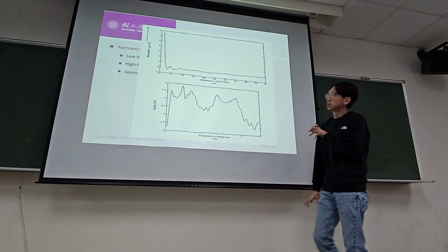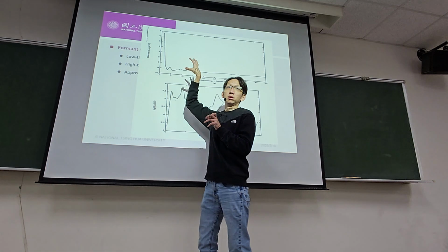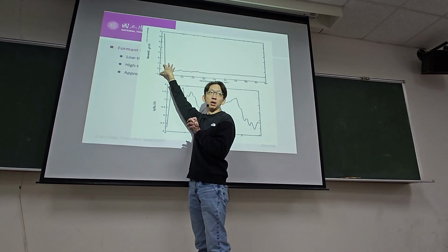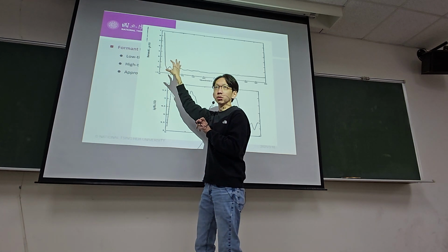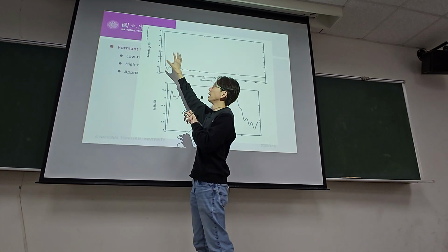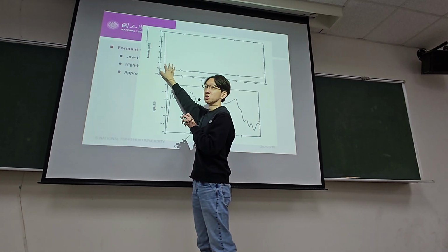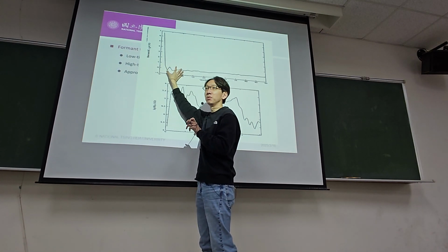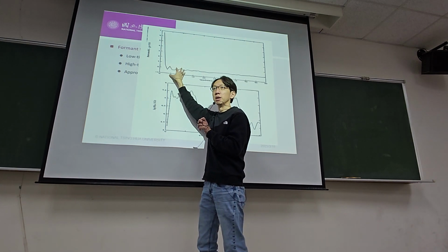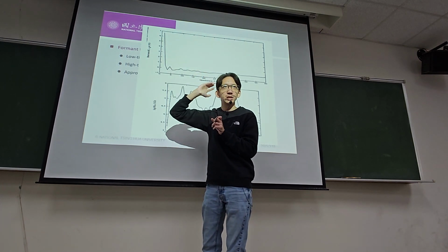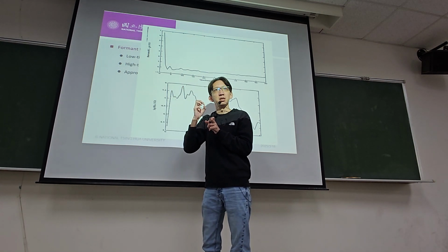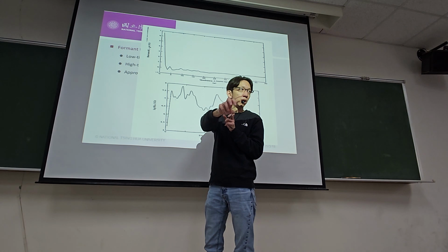When you take a portion out of your cepstrum, you are applying a window function on your cepstrum. If you apply a rectangular one, you just take it out. Or you apply a window function so that it doesn't change too much of the frequency property of the cepstrum. That's the parameter weighting method of taking a segment out of the cepstrum. It's the same process as with your time domain signal, where taking a segment out applies a rectangular function.